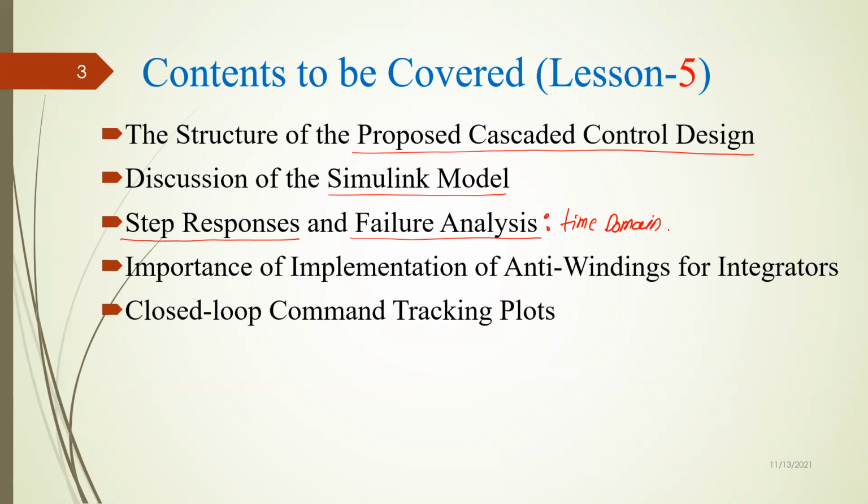And then we would also like to see the importance of anti-windup. In my 4th video, I mentioned that anti-windup is very important, especially when you use saturation in your control block and our control signals are saturated. In that case, our integrator integrates the wrong value. So we need anti-windup for integrators, and we will see the importance of that. And at the end, we would like to see the closed loop command tracking plots. So this is your frequency domain plot.